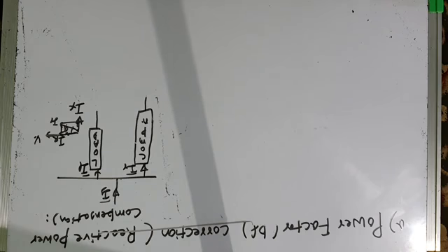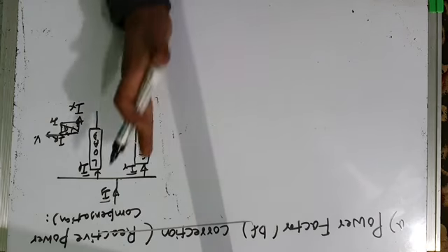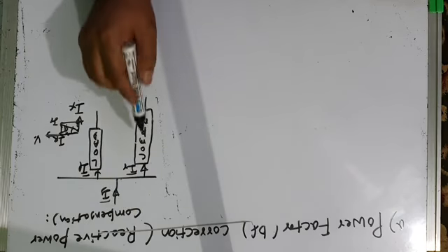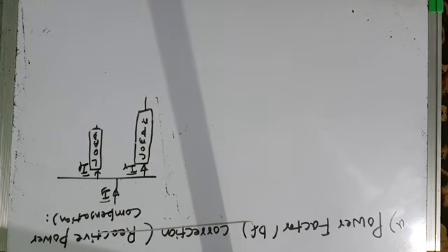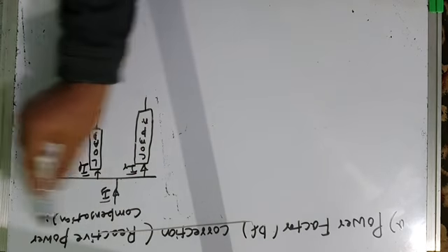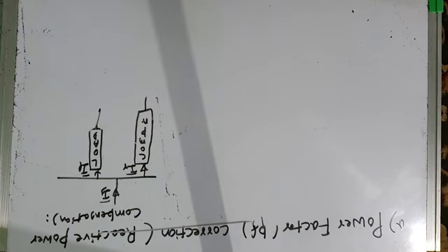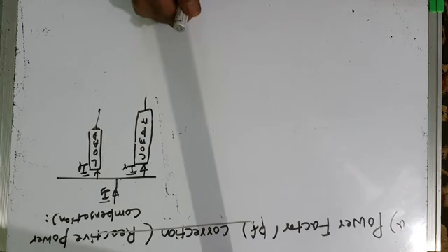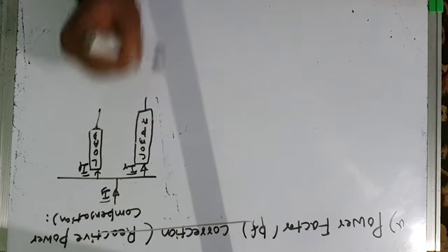Okay, now, I have already told you that when you connect the compensator across the load for load compensation, what type of compensation has to be done? Reactive power compensation or power factor correction. So this is how it does it. Now you have to calculate the apparent power rating of this compensator. If your load is 10 MVA, what will be the rating of the compensator?